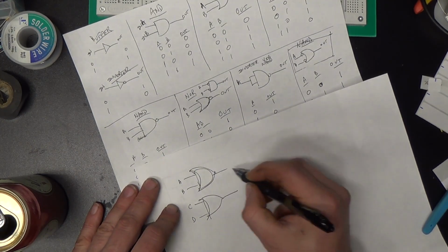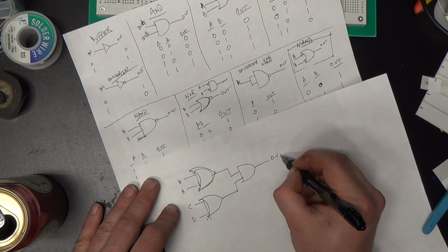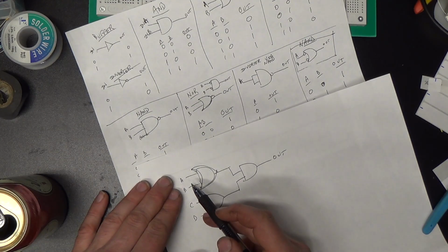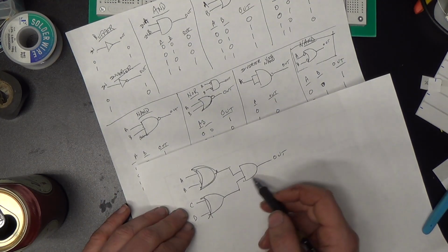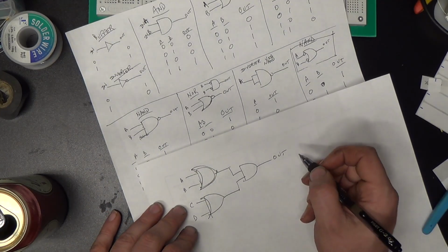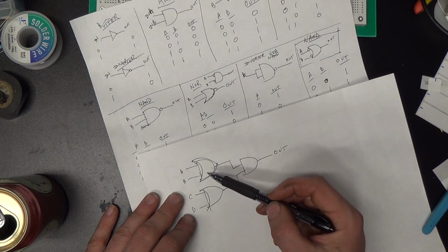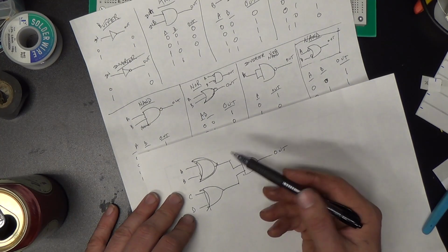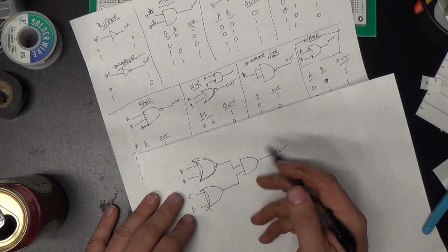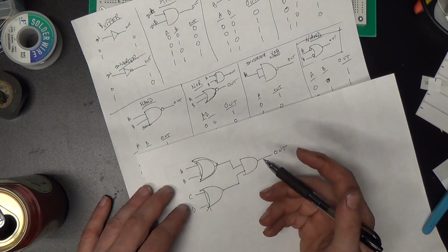Sorry, I'm dumber than I look. And then that goes into an AND gate, and we've got an output. So if A or B and C or D are asserted, then the output will be asserted, right? So this would normally take, I mean, you get 4 2-input gates on a 74 series logic chip. So normally you'd have to have 2 separate chips to do this. Very inefficient space-wise and money-wise, right?